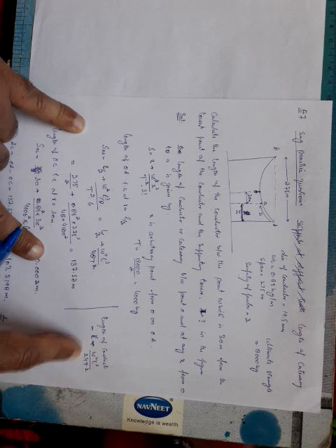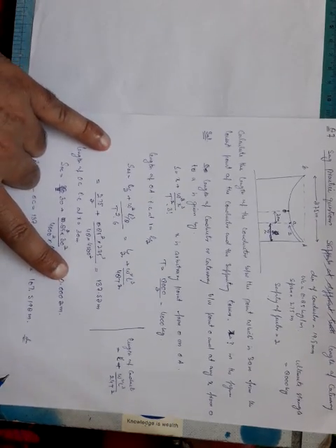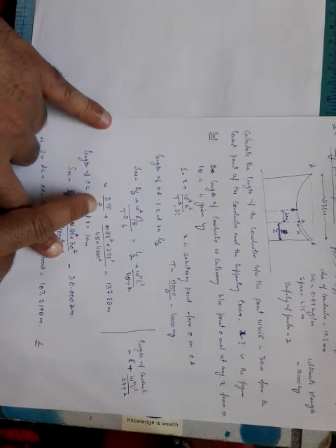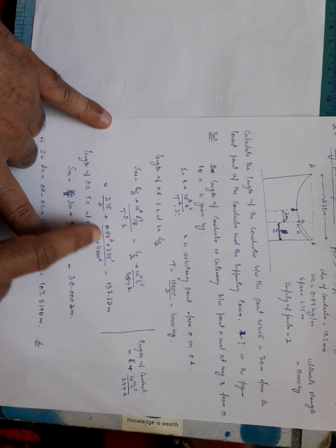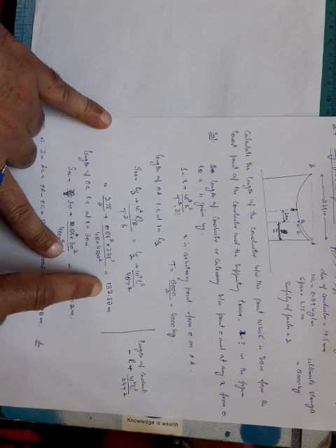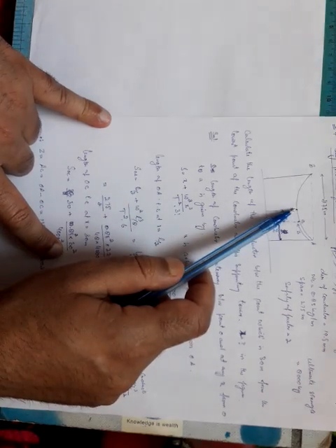So this has actually been derived from this equation, but I have given this extra information. We need to calculate this half length. So when I put the different values, it comes out to be 275 by 2 plus 0.85 square into 275 cube divided by 48 into 4000 square, that is 137.52 meters. This is the length of OA.